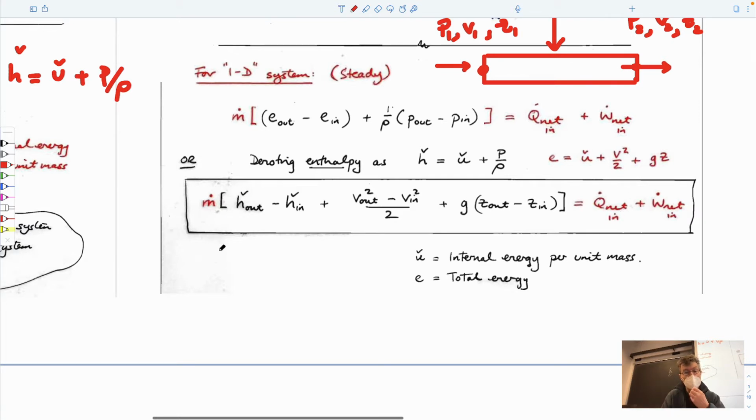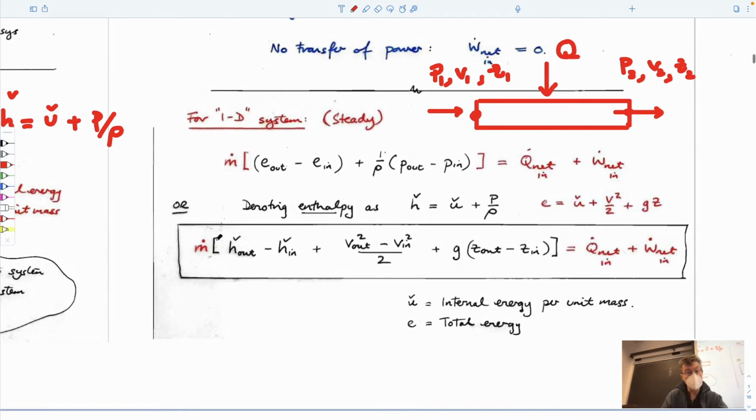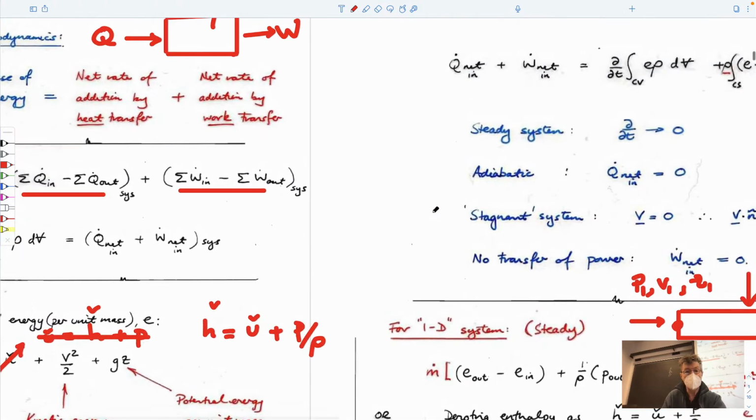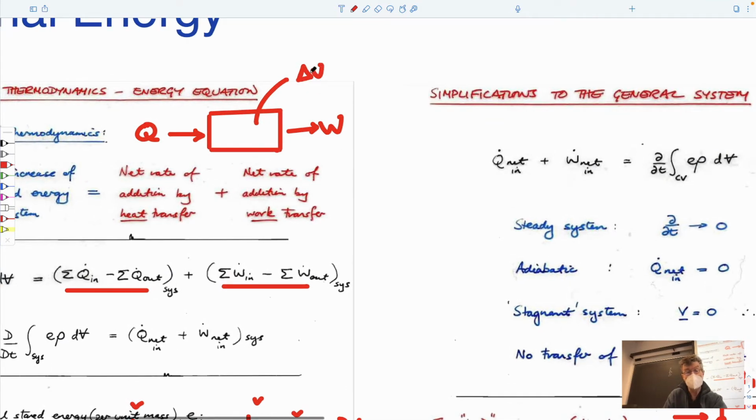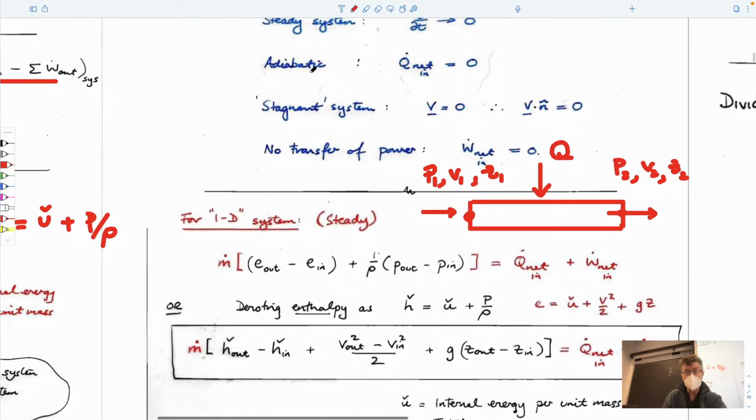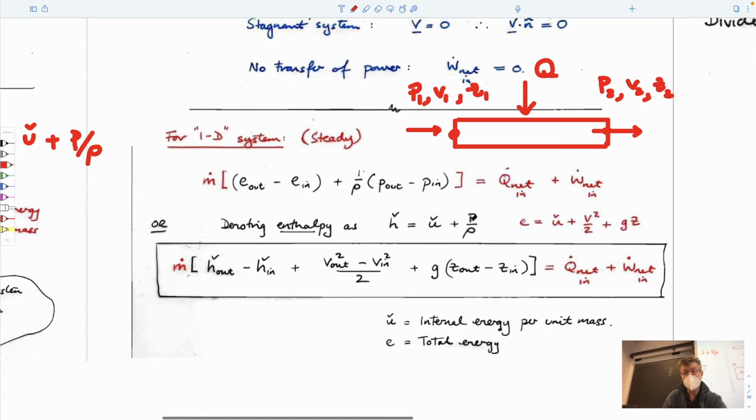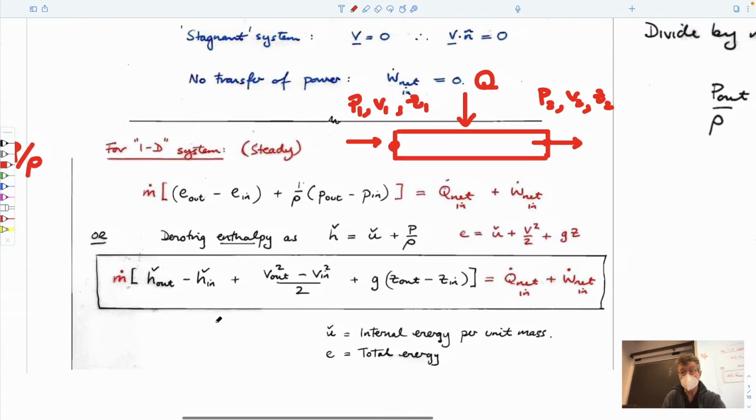We didn't use it, or we used it sparingly, because we didn't do very much with thermal energy in the system, with enthalpy in the system. But you see that we have the velocity head term, the elevation term, and wrapped into the enthalpy, we have both internal energy per unit mass, which is this portion that is defined in terms of the change in the energy of the system, plus the pressure, instead of being with these terms, is just wrapped into the enthalpy. And so that's kind of the system that we'll deal with.